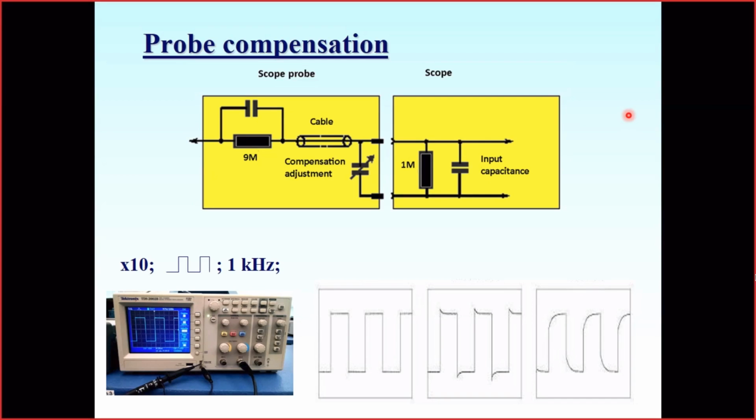For instance, if we are going to measure the voltage over a certain resistance in a circuit, and this resistance is comparable with the voltmeter resistance, then when we attach the voltmeter to this resistor, we actually shunt it, and part of the current will be driven through our voltmeter. This totally changes the current in the circuit and may change the voltage across this resistor.